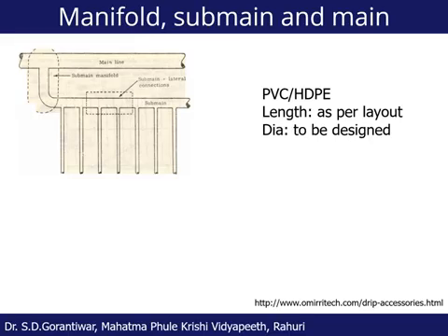If it is exposed to the sun for a long time, there is quite a possibility that it will become brittle and develop cracks even after 1 year. So when you use PVC manifold, submain and main, take care that they are buried in the soil. But if you use HDPE, no problem. You can install those on the soil surface.